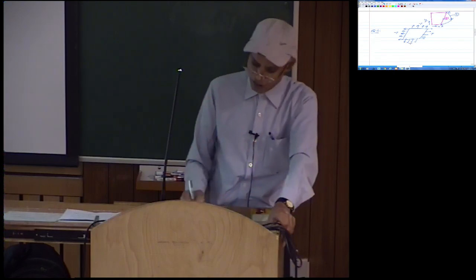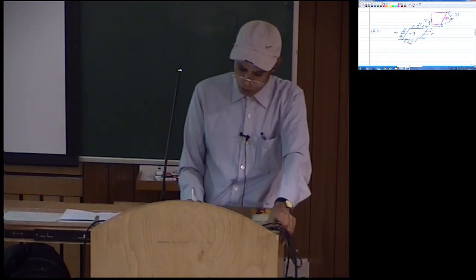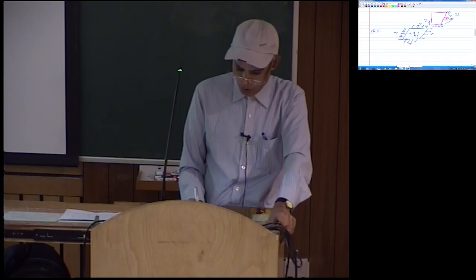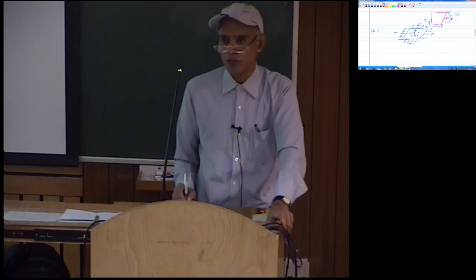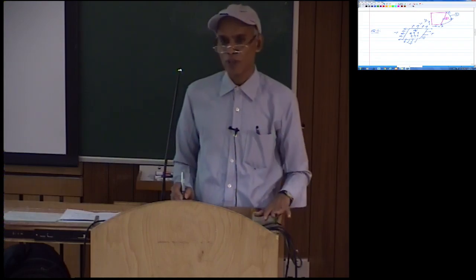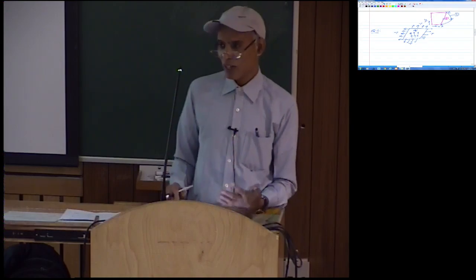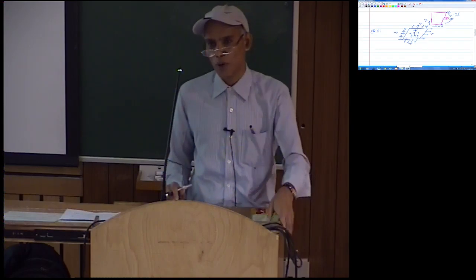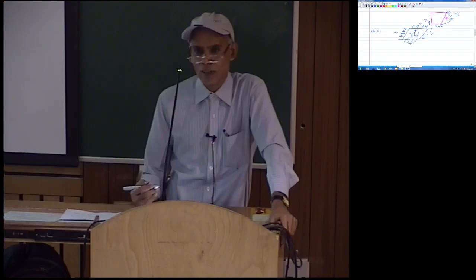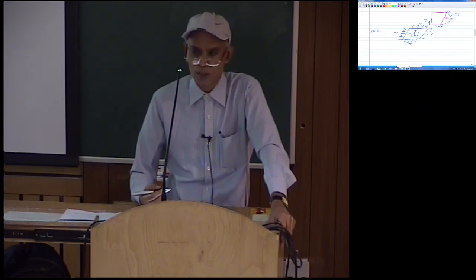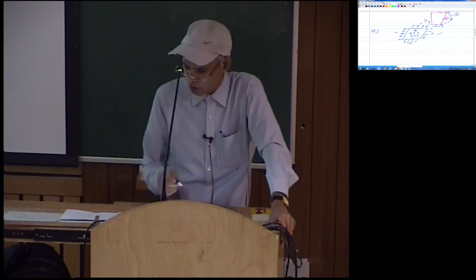This is in-plane tension, and then there is a transverse load Q. So for that, the differential equation was given, and I had asked you to develop the element level governing equation considering a 3-noded triangular element. So differential equation, weighted residual statement, weak form, and then integral functional, or from there you can develop the element level governing equation. So that is what I had discussed.